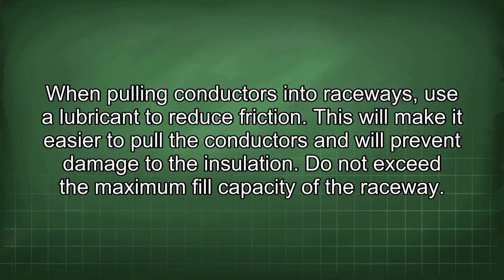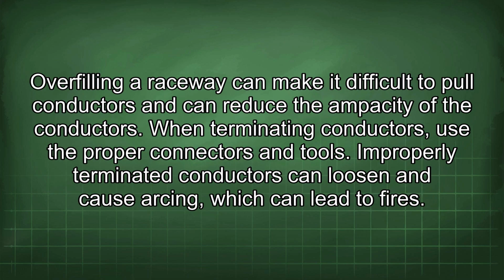When pulling conductors into raceways, use a lubricant to reduce friction. This will make it easier to pull the conductors and will prevent damage to the insulation. Do not exceed the maximum fill capacity of the raceway. Overfilling a raceway can make it difficult to pull conductors and can reduce the ampacity of the conductors.